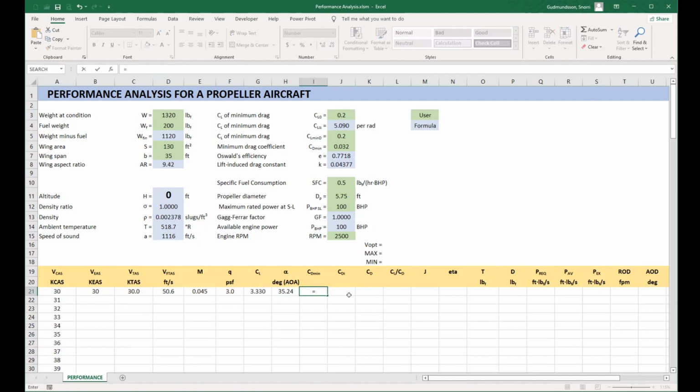This is really done in case we want to plot it. However, for detailed analysis, this value changes with airspeed and should be calculated for each speed. This is a consequence of change in Reynolds numbers, which affects the skin friction, which in turn affects the extent of separation regions and thus pressure drag. At lower angles of attack, this is captured using the appropriate form factor during drag analysis. This requires substantial effort to prepare, and if you happen to be a student in my design class, you will have to do this for the airplane you're designing.